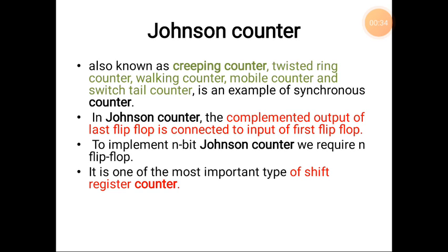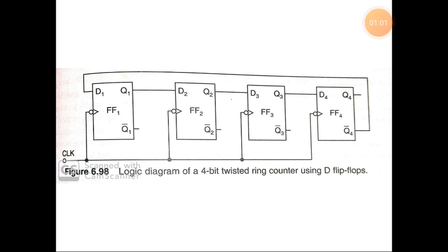We know that this is a counter that is obtained from a serial in, serial out shift register by providing the feedback from the inverted output of the last flip-flop, that is the complement output of the last flip-flop, to the D input of the first flip-flop.